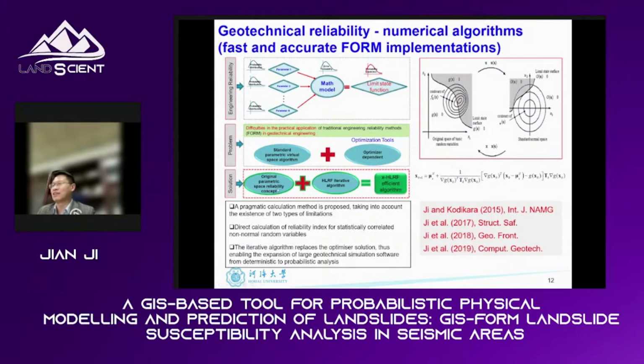We developed a new concept for an iterative algorithm based on the HLRF, Hasofer-Lind Rackwitz-Fiessler, which is a sub-algorithm of the first-order reliability method. We developed this iterative algorithm in the original space of random variables, resulting in our efficient algorithm called HLRF-X.